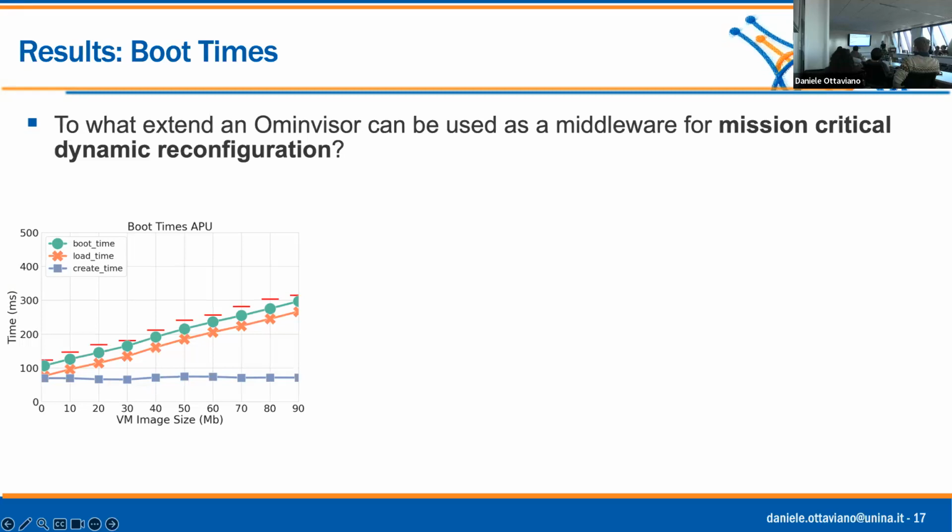That's the scale: hundreds of milliseconds. We change the image size, and we divide the boot times into three parts. The creation time is the time in which the hypervisor just creates the structures and removes the pool of resources to give to the other virtual machine. The load time is the time in which the image is loaded in memory, and the boot time is the time in which the CPU is started, or taken out from reset.